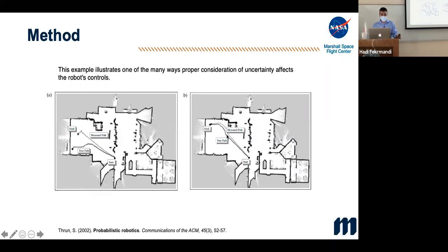But if it is further away, as in the picture on the left-hand side, the perception of the robot deviates from where it actually is, and that's where we have the problem of a lost robot. The same thing that happened to the Soviet robot can happen here. If we want to do something meaningful, to really localize where the robot is and have accurate data from the samples, that is not acceptable. So we want to make sure that our robot does have uncertainty, but can handle it.